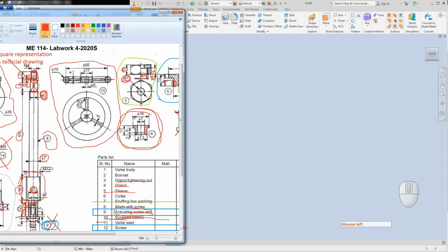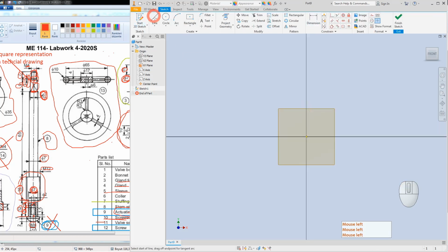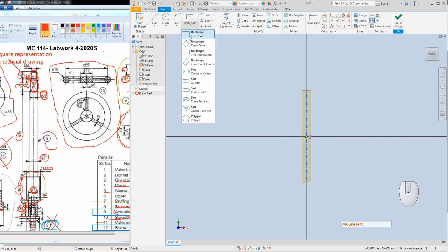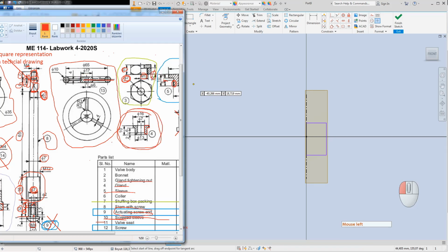Let's move a little bit more. This time I'm going to select the midpoint center upon this. From the top side, we can make a revolve section. Start a new plane, a new line with horizontal constraint, take midpoint to this midpoint, convert it to center line. Here I will make the full side, a rectangle starting from this point, another rectangle. Let's make this part later. A new line for this center line. I'm just going to make a center line and connect this ring, this donut shape.